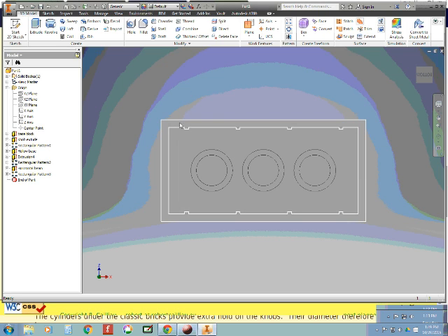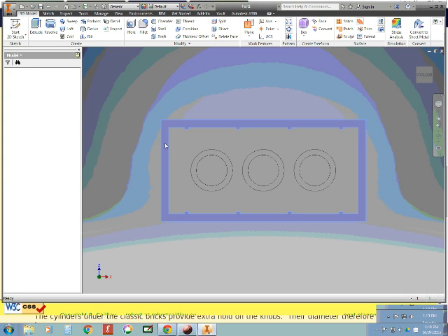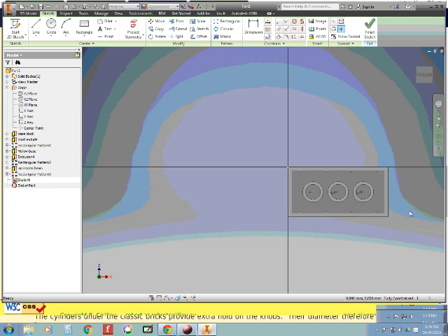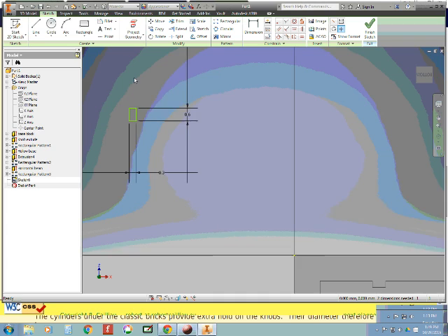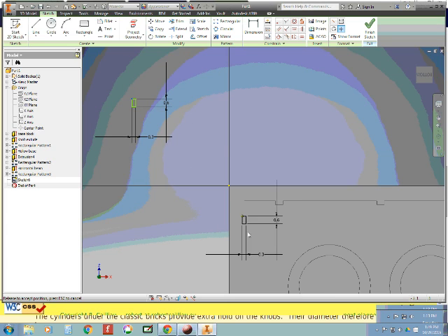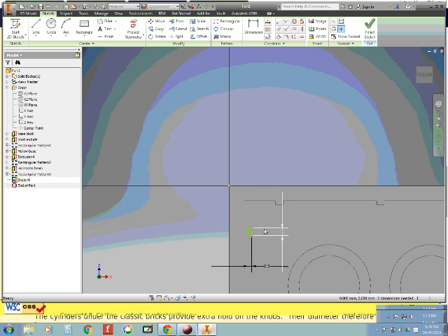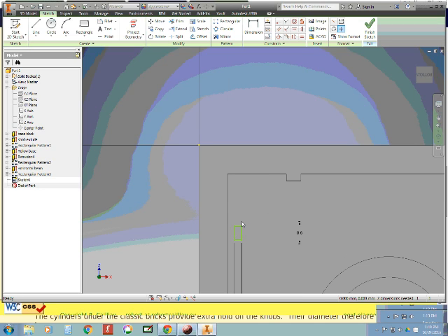Okay, so once again, create a new sketch. I'm going to right click, new sketch. Draw my rectangle up here. It is 0.3 wide by 0.6 tall. Turn off my constraints by pressing F9 so that I can see what I did. Bring it down to my drawing, and once again we got to constrain its position, and there we constrain the midpoint of this line to this line. So we went up here to coincident constraint, which allowed me to grab this midpoint and put it here,